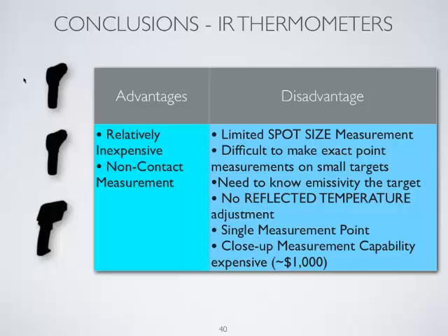However, this limitation is overshadowed by the inability to enter any reflected temperature information. That is a critical parameter in making the mathematical calibrations to present a temperature value. Now, the single point measurement also contributes to the difficulty to accurately pinpoint the target of interest. This increases the time it takes to sample targets.